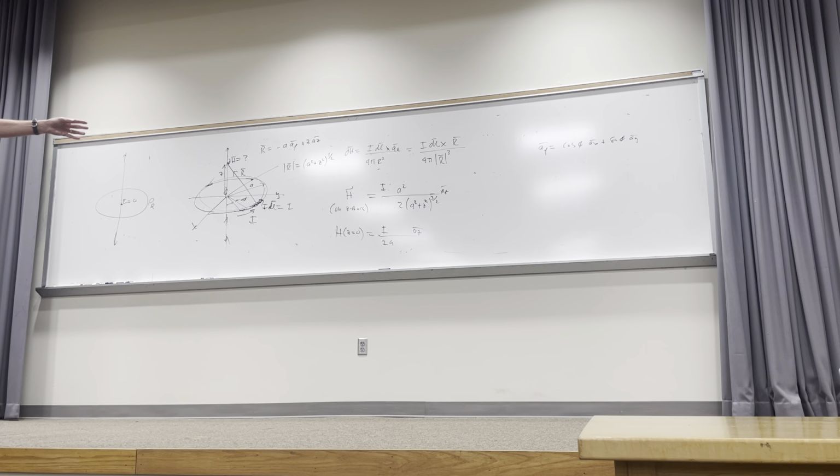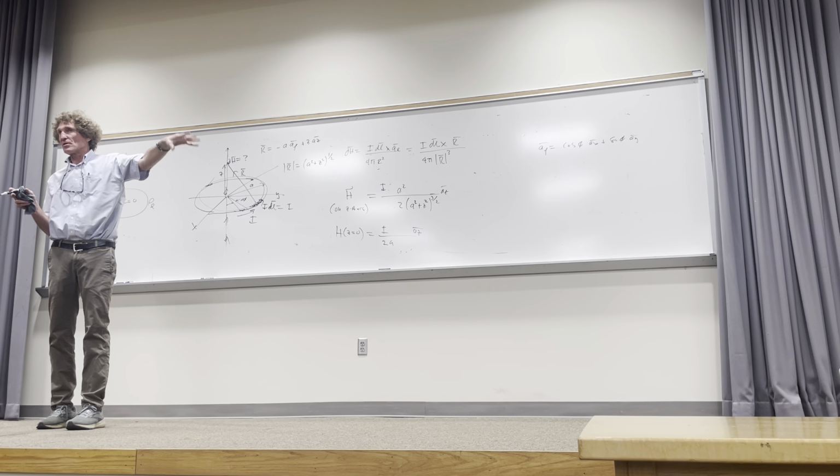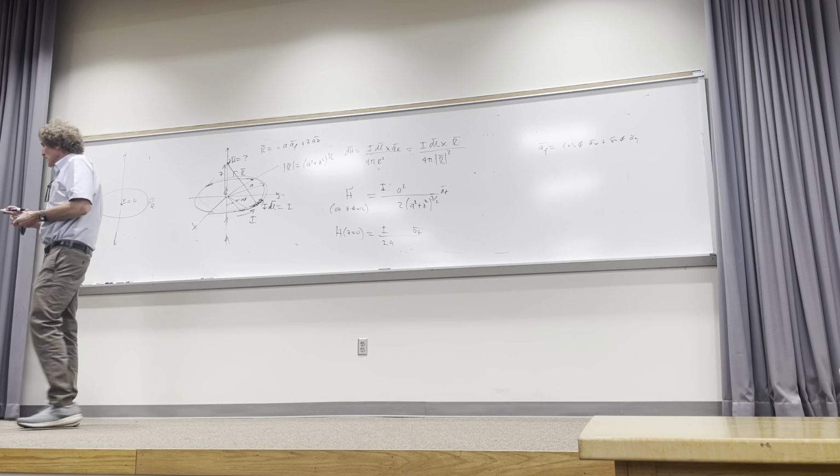What happens as z goes to infinity to the H field? Last comment. Just look at the equation. Make z go to infinity. What happens to the value of the H field? Zero, and it has to go there. Anytime you have an infinite distance from a finite amount of current or charge, the value of the field quantities, D, H, E, whatever, have to go to zero. Do you follow me on that? That's a simple check, a mental check.